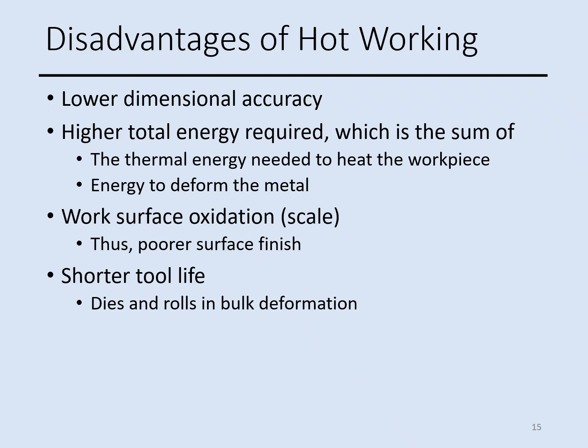And oxidation may happen if the part is exposed to some gases in the atmosphere, which is not favorable, for example nitrogen. Then you will have a poor surface finish. And the tool life in hot working is shorter.